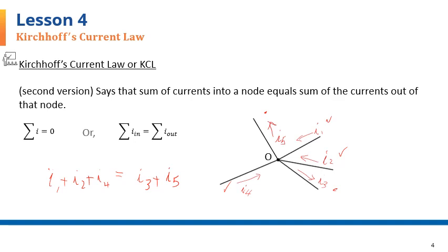As you can see, the KCL gives us an equation for any node that we look at. So if in that node the currents for n-1 branches are known, then the last current, the missing current, can be calculated based on this single equation that comes out of KCL.